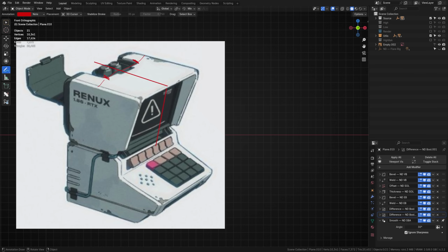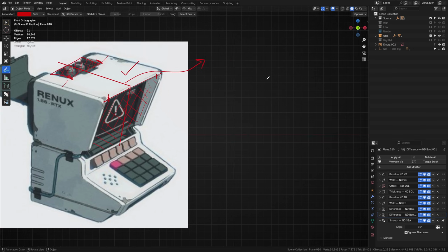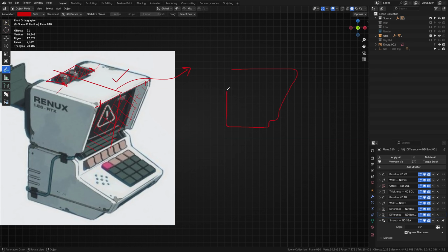So my brain is telling me that that's a subtractive detail. What about the front? We also have a large cutout. It looks like subtraction again. So, would we have a deconstructible shape if we use some geometrical putty and filled in the holes? It looks like it. If we take the cross-section formed by the plane and draw it out to the side, it looks something like this. Awesome, we have a sketch. If we can start with this and extrude it to the required width, we can add the remaining details via subtractive, aka Boolean, methods. Let's jump over and take a look.